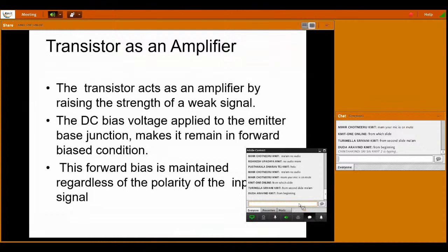Actually, today we're going to learn about the transistor as an amplifier. Till last class, we only discussed the response after applying DC signals. We did DC analysis and did not provide any AC signal. From this session onwards, we're going to apply an AC signal for amplification. In addition to the DC signals, which were used to operate your transistor in the active or linear region and set the operating point on the DC load line.